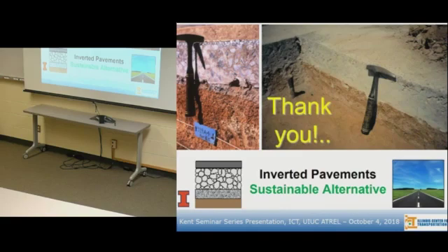However, what we know is that although the Georgia DOT typical design was applied in the whole road section, there was a slushing technique that they tried to apply. And the typical compaction of the aggregate base, according to Georgia DOT standards, both were quite low in FWD deflections. So whether or not we have to go through the slushing, we may not be able to do slushing as well as the South Africans, but even the typical base course construction, achieving high enough density, may be enough, because we're achieving quite high densities now over a stabilized base or subbase. So the base course goes up to very high densities. I think that still brings out the good qualities of the aggregate. Not the highest quality, but maybe medium quality, and unless it is crushing, it will perform very well.